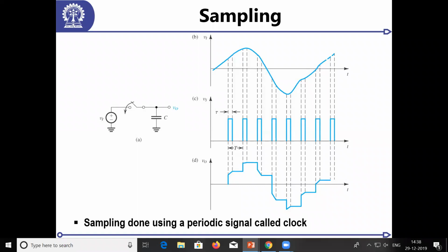All you need to know is only one equation for a transistor. Let it be the square law equation. That is good enough. All those transistors have deviated from square law because of scaling, because of velocity saturation. I don't know if you know this term already. As technology scales, the speed of the electrons is limited, so you hit something called velocity saturation.